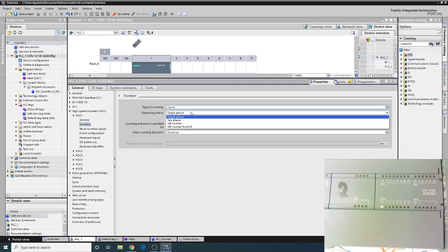So basically, the high-speed counter is its own little dedicated device with what's called interrupts in it. Anytime that click changes, it stops what it's doing, runs the interrupt code, which basically says count up or count down, and goes back to what it was doing. Then every loop of code, it just goes to that high-speed counter cache and asks, hey, what's the counted value? And it says, oh, thanks, we're at 600 now, or we're at 800 now, whatever it is. So the main PLC program doesn't actually have to keep track of that.